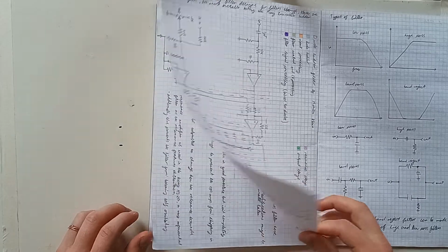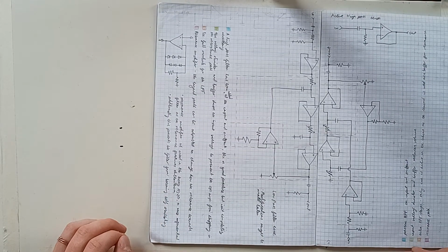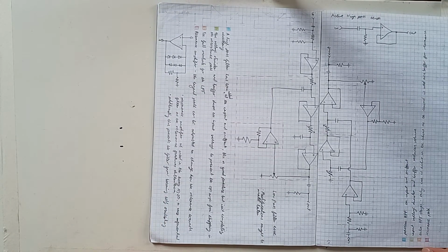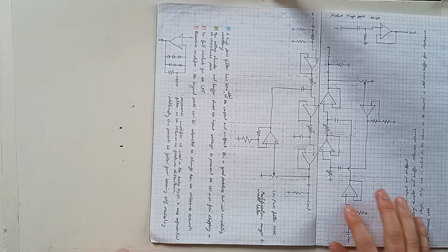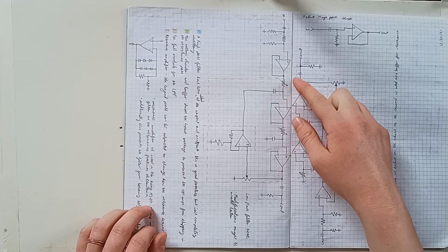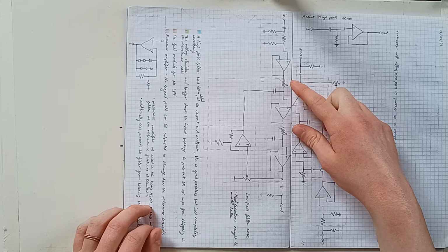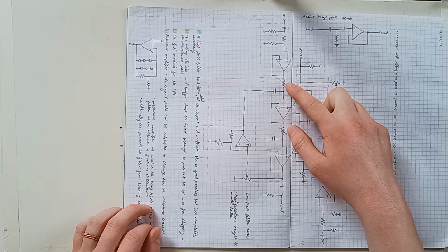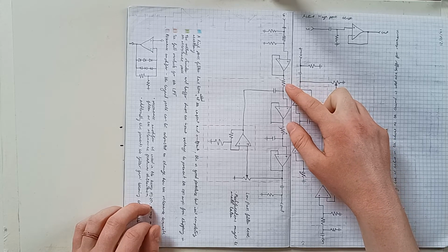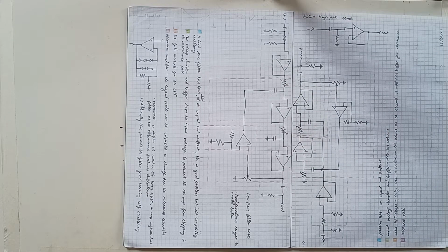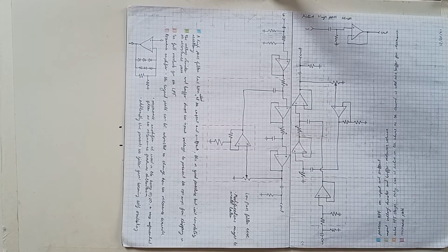And it's important to note as well that that is a much more efficient way of controlling a filter than in a cascade filter, because as I said in the last video, these have to change their resistance at the same rate, otherwise you don't get an even cutoff curve.